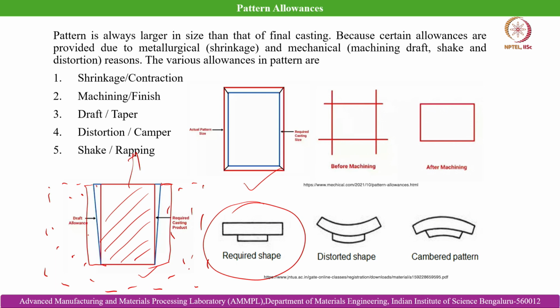Because of the residual stresses created during cooling of a cast object having different cross sections, we often end up with a distorted shape of the component after freezing. Such a distorted shape can cause total rejection of the cast part, because it cannot serve the dimensional attributes necessary for its intended application.